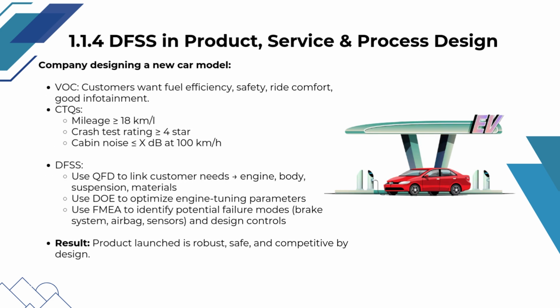In the example of a company designing a new car model, DFSS begins by capturing the voice of customer around fuel efficiency, safety, ride comfort, and infotainment, translating these into clear CTQs such as mileage of at least 18 km per L, a minimum 4-star crash rating, and controlled cabin noise, then using QFD to link customer needs to design elements like the engine, body, suspension, and materials, applying DOE to optimize engine tuning, and conducting FMEA to identify and control potential failures in systems such as brakes, airbags, and sensors, resulting in a product that is robust, safe, and